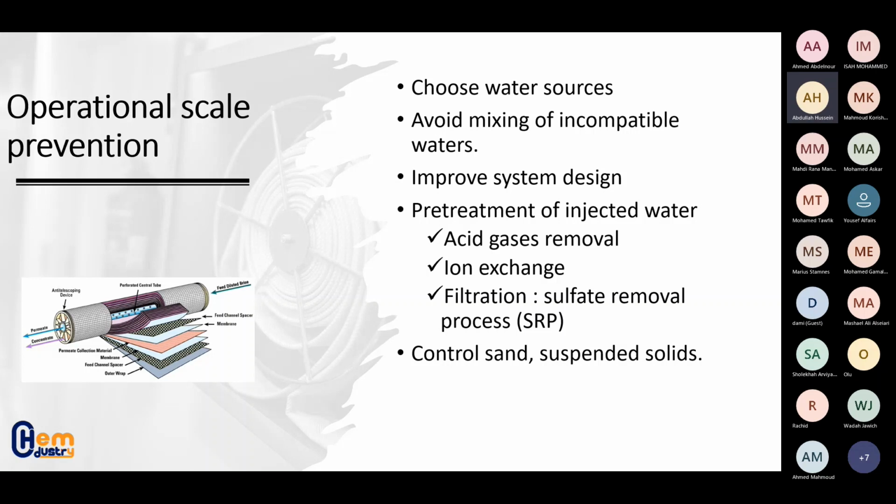And also the injection water systems. You can pre-treat these, removing the dissolved acid gases, using ion exchange, and recently removing the scaling ions. And this is a very common technique people are using right now. It's called the sulfate removal process.